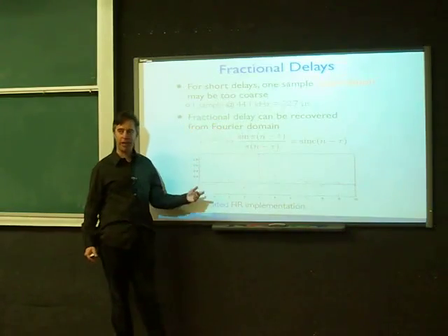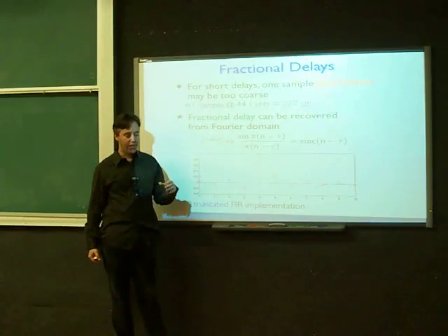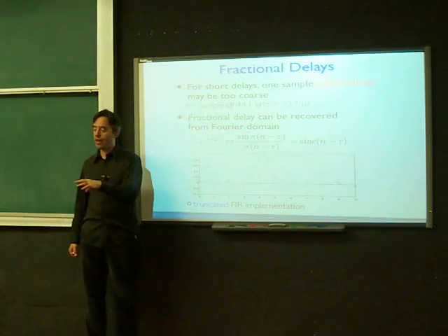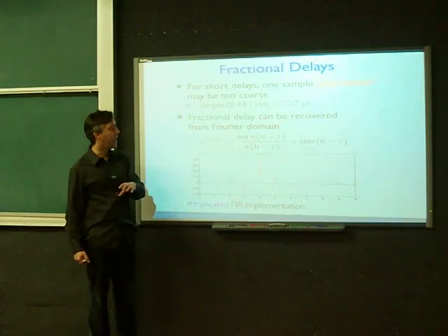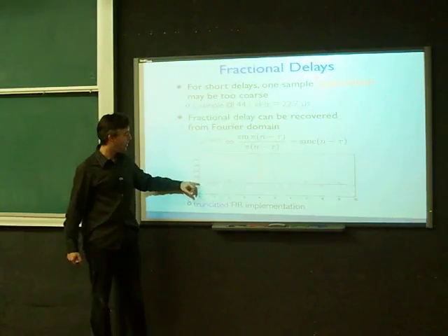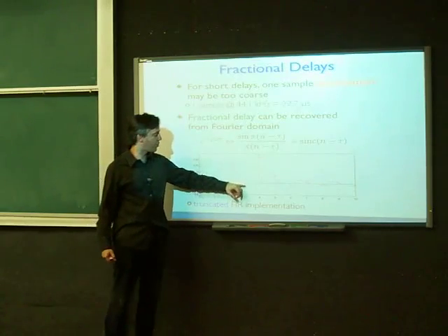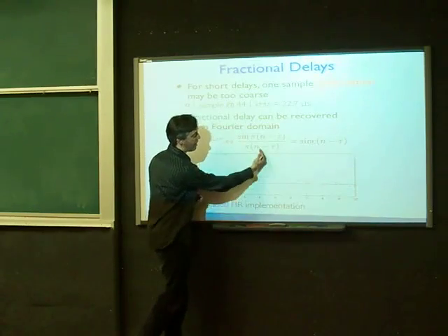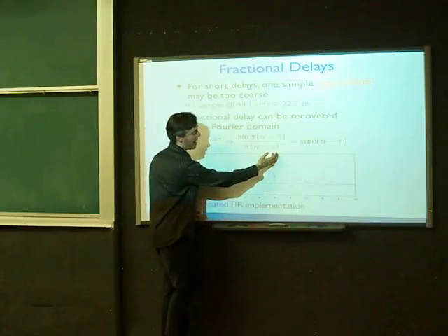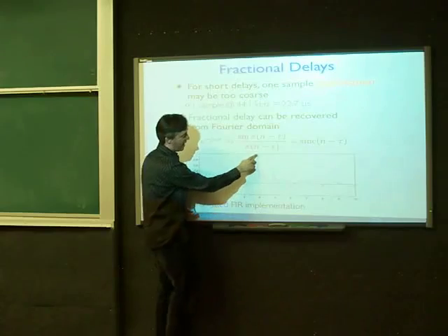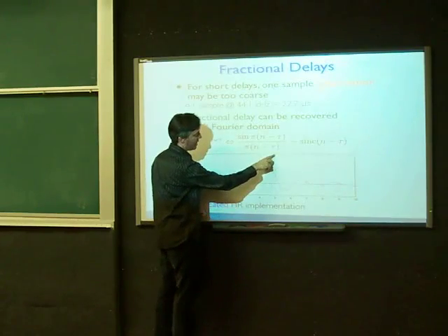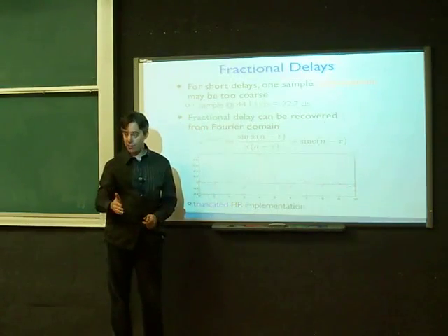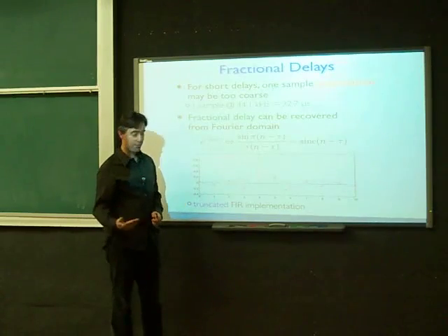We saw that when we were looking at upsampling and downsampling in DSP. So you can do away with the intermediate sampling rate and just say a fractional delay is samples drawn from this continuous sinc function, centered on whatever actual delay I want. If it happens to be centered exactly on a sample, then the point you sample is 1, and all the other points occur at the zero crossings. So you have an impulse response which is just the integer delay of samples, as we expected.